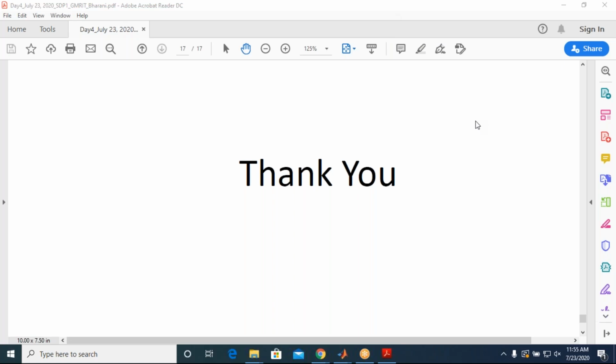How to solve data type mismatch error? Relational operator output is Boolean, but transfer function requires input double. Saurav Kumar has answered: use data type conversion block and decide yes.